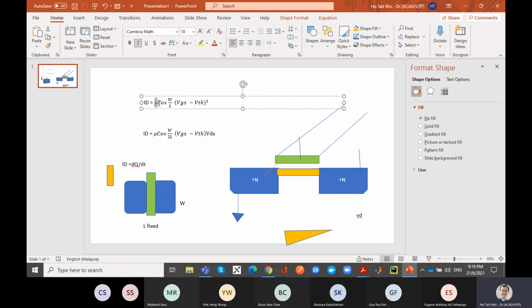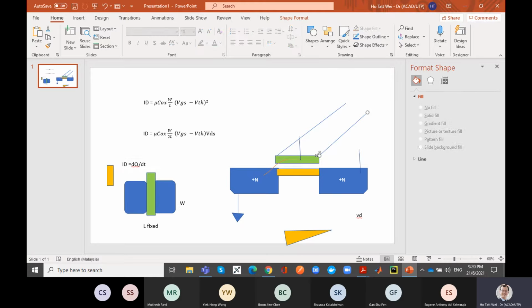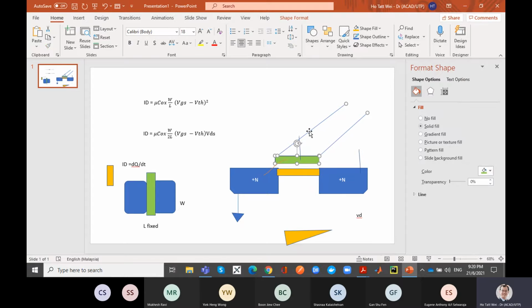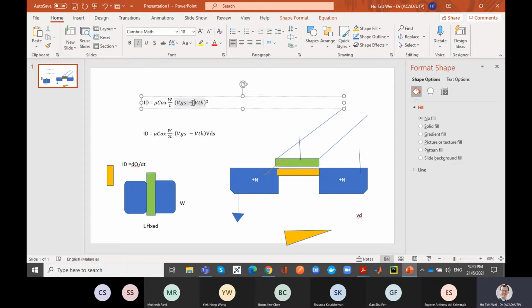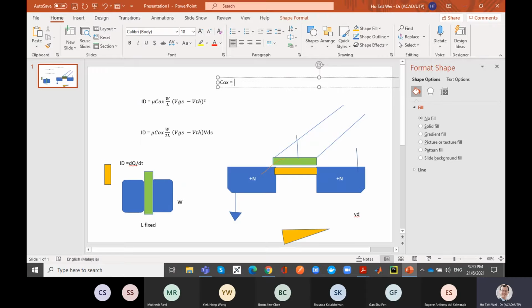Okay. And the fourth way, of course, is I reduce the capacitance, right? Because capacitance is a function of area over distance. So again, if I increase the width, I'm of course increasing the area. But if I reduce the distance like that, I can have more current because reducing this distance will increase the capacitance, right? Because you remember your capacitance is basically nothing else but Cox is epsilon A over D. A is the area here, D is the distance here.